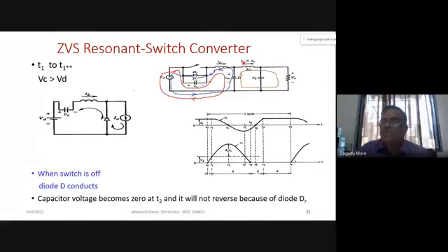So I0 is constant and ripple free. We assumed this I0 is constant and ripple free. Whenever this current tries to decrease, the diode will definitely turn on, and whatever energy is in the inductor will be dissipated through this. So our diode is on, here this is I0 and the diode is on. And as the diode is on, we now have an LC tank circuit.